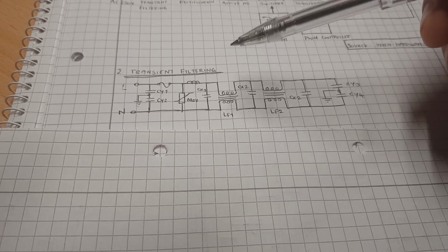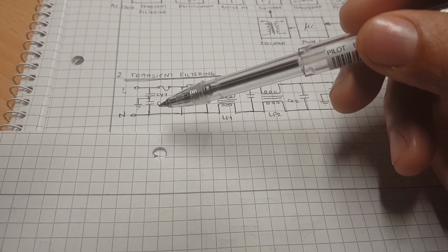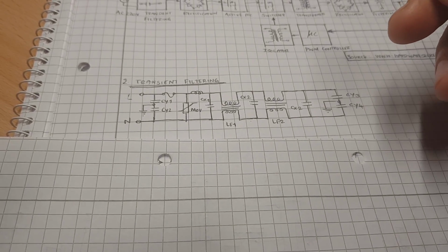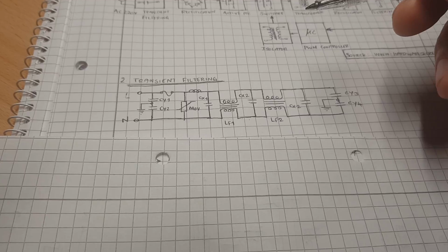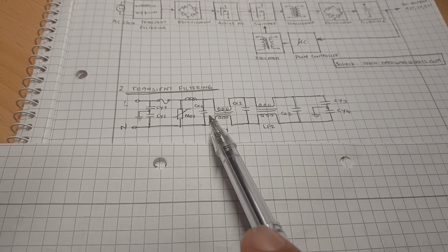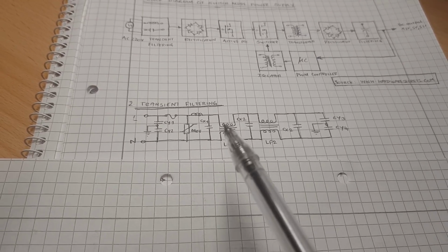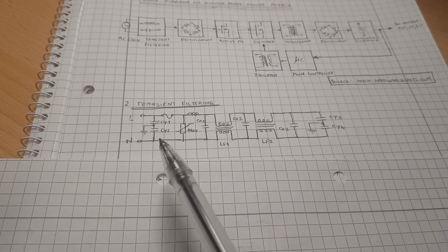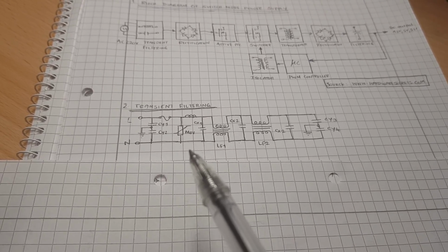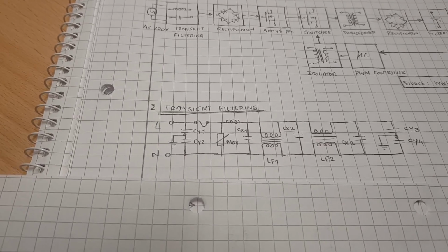The capacitors in the beginning, which is also connected to the midpoint in the ground, is called CFYs or capacitor Ys, Y capacitors, and the remaining ones are X capacitors and X inductors, and that's why you see this designation CY and CX, LX and LY. Okay, I have marked it, but so these are the X capacitors.